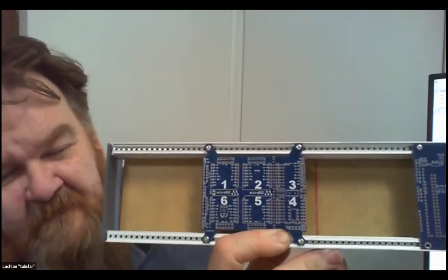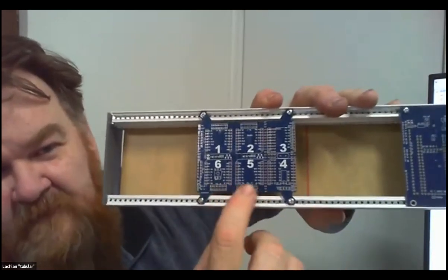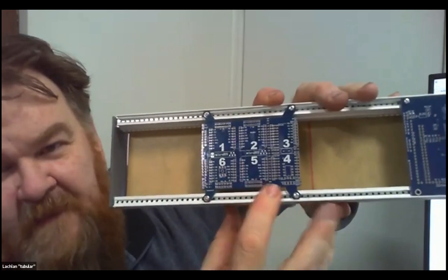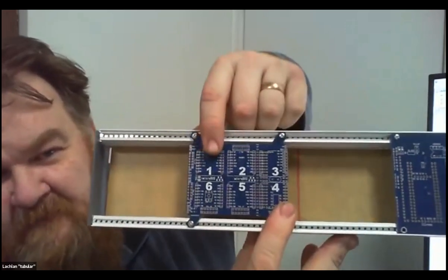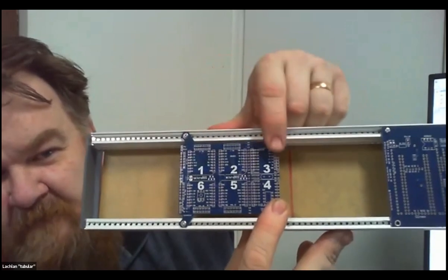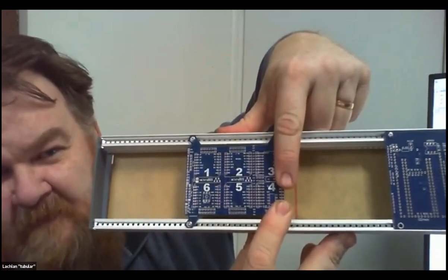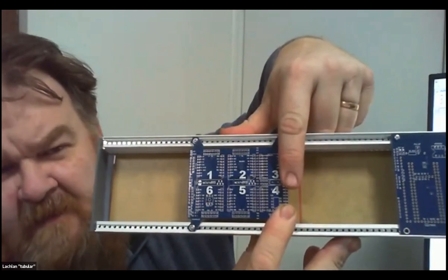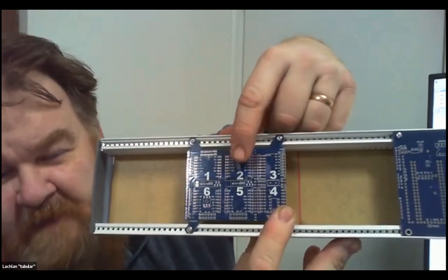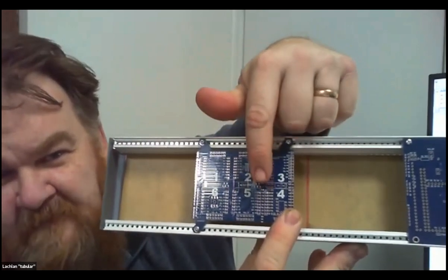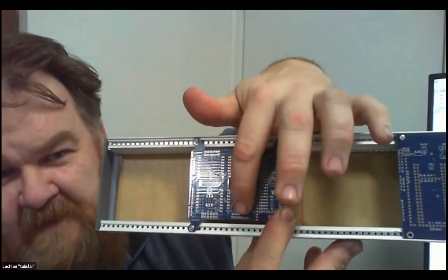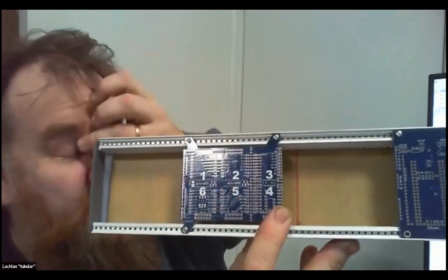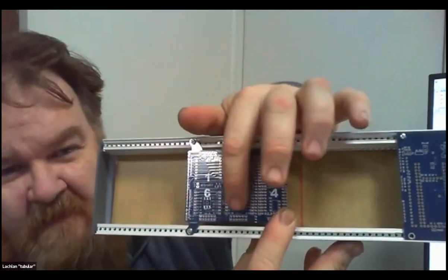That represents 72 pins, doesn't it? Yeah, so on Click modules 5 and 6, we did actually multiplex the modules. We took 12 pins for P1, 2, and 3, 4. Each one is a 16-bit word of I/O, and then we came back and used P12 through to 15, so the 4-bit nibbles are used to make up Click 5 and also Click 6. They're kind of in parallel.